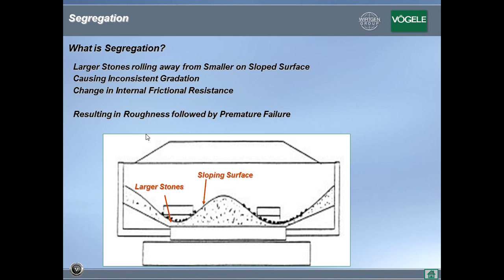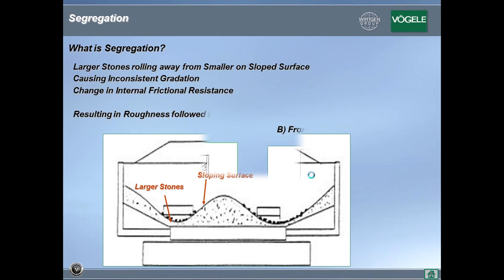Now, seeing that we don't manage the plant, we're only dealing with the pavers, so we will not be looking at any segregation or potential segregation that could be created at the plant. We'll be only looking at segregation from the truck, when the truck delivers into the paver, when the paver delivers to the screed, or when the material transfer vehicle delivers to the paver. So as we said, if you create a sloping face, the larger stones on this face roll down, gather into the valley there, and you'll have a pocket of segregated mix smack in line with the center of the conveyor. Likewise, you would have on this side.